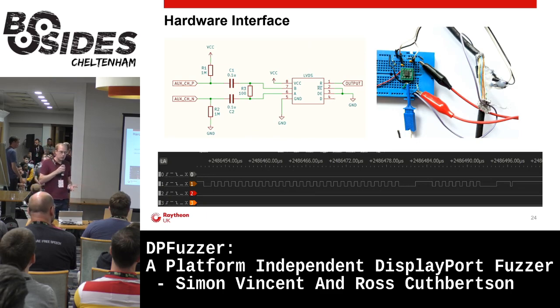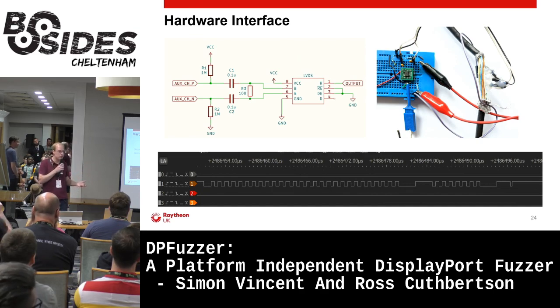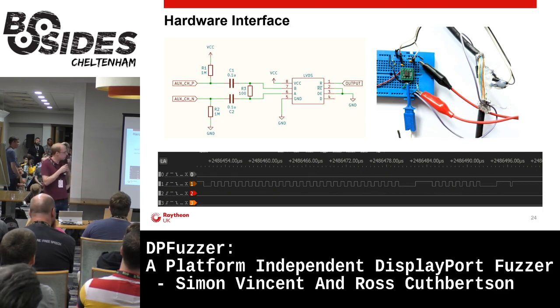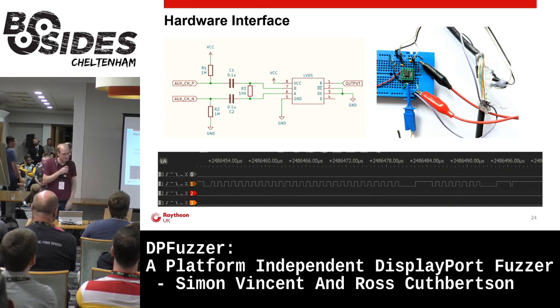So this is the circuit we came up with to start. You can see all the discrete components there are connected to the DisplayPort channel, and that goes into our LVDS chip. And then we've connected the output of the LVDS chip into a logic analyzer. On the bottom, you can see the sync frames, then the end of sync flag, some data, and an end of data marker. And on the right, it's just a little picture showing our initial prototype, pretty nasty. Essentially, we took a knife to a DisplayPort cable. But it works, and it's quick.